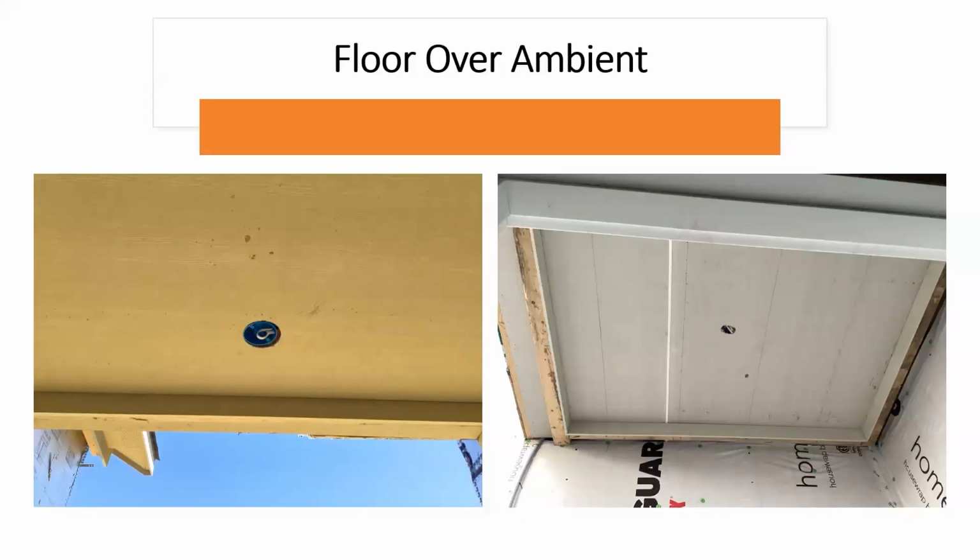We can't forget these, though. If insulation is not visible for inspection, really what the verifier should do is grade everything that's not visible as a grade 3. If you can't see insulation, or hopefully you can see insulation around the openings, so you know it is insulated, it should be graded as a grade 3.